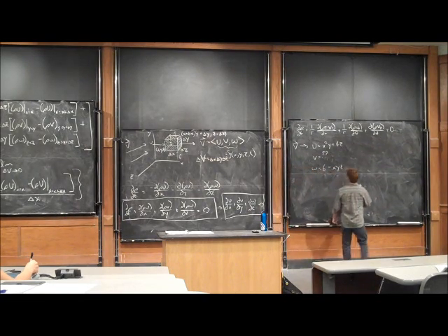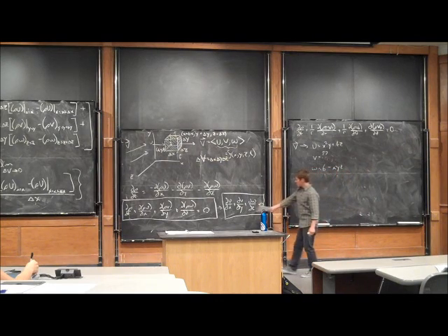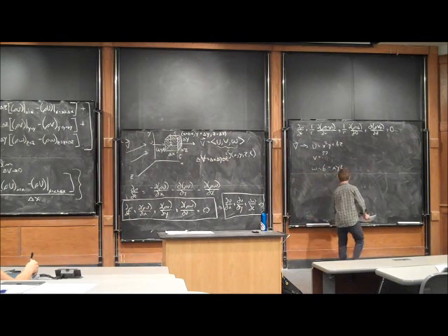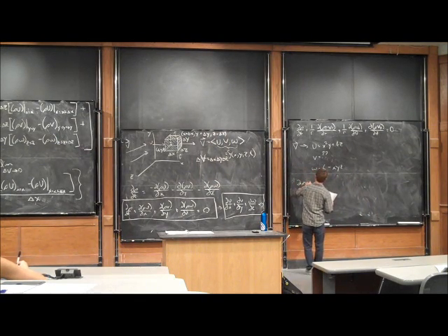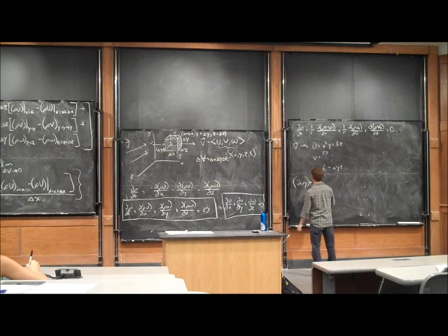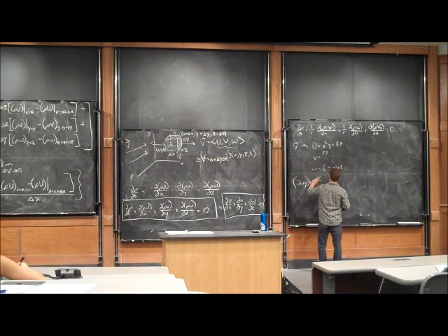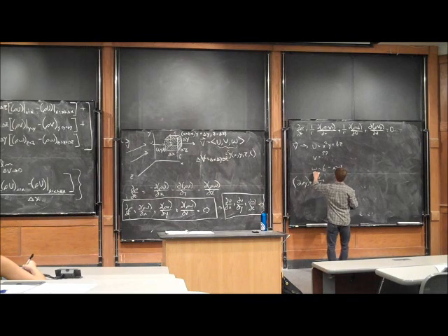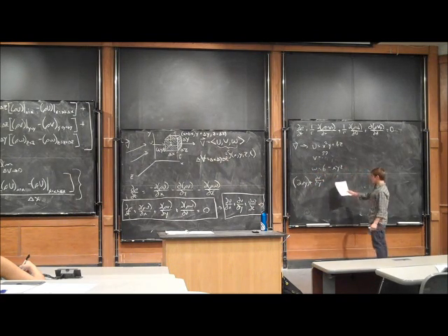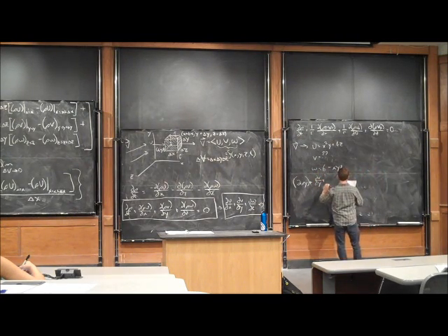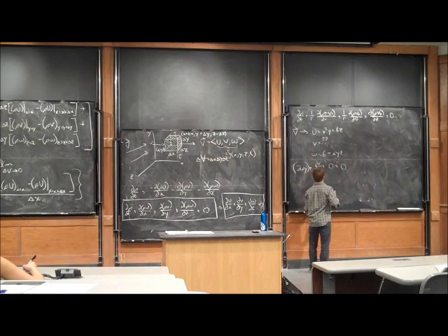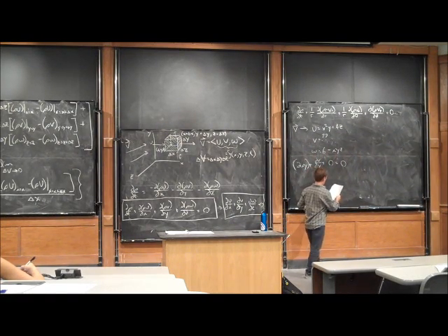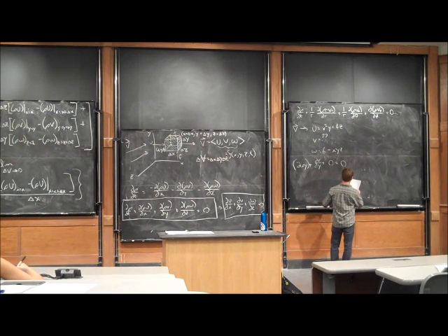If we assume it's an incompressible flow field, we can use this equation right here. We know that ∂u/∂x is going to be 2xy, plus ∂v/∂y, which we don't know, plus ∂w/∂z, which is going to be... Isn't there a z? Minus xyz? Yes, you're right.